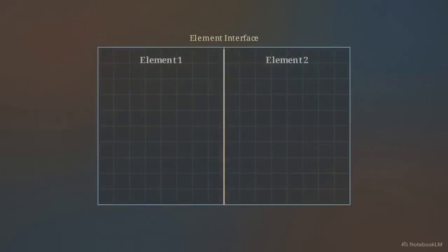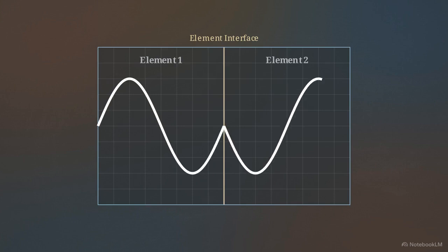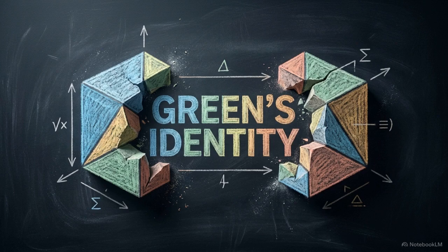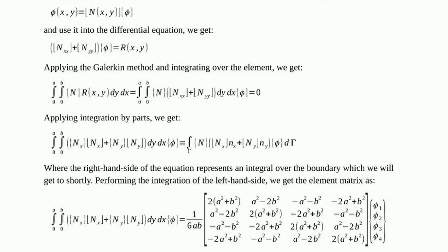In finite element formulation, second-order derivatives demand higher-order mathematical continuity between adjacent elements, which increases the complexity for a computer to process. To resolve this, we apply our second mathematical tool, integration by parts, relying specifically on Green's first identity for two-dimensional space. This operation mechanically alters the integral, splitting the single equation into two distinct parts. Notice how the derivative terms inside the new left-hand side integral have dropped in rank. The second-order variables are gone, replaced entirely by first-order derivatives.